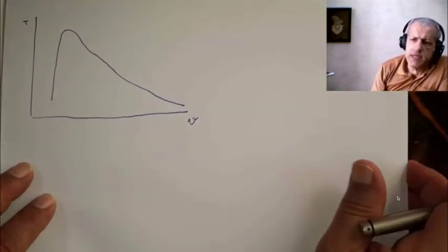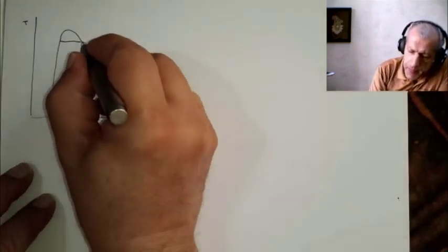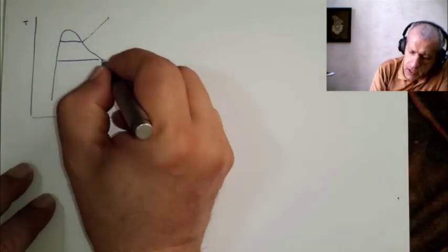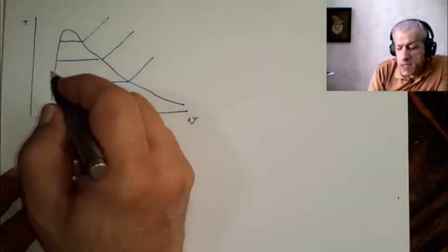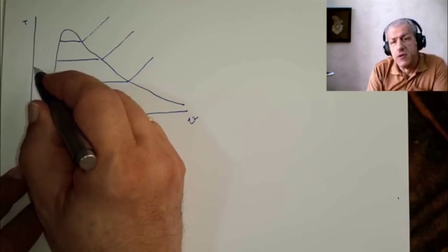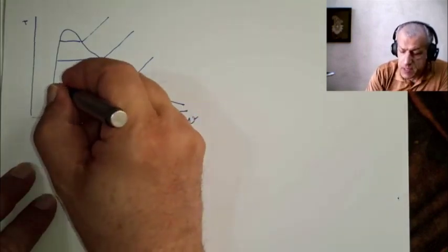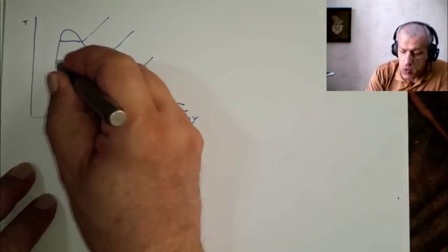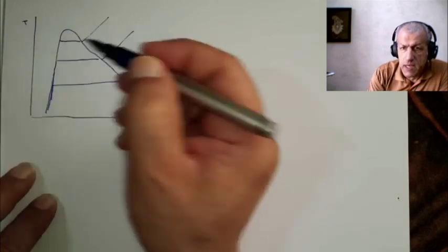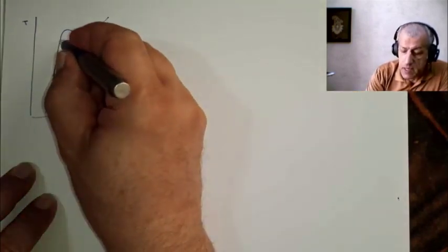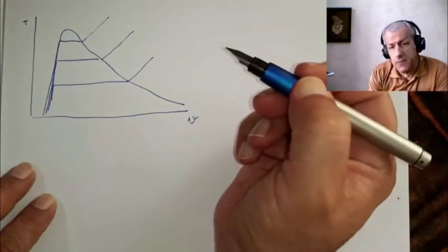So what we do is to draw a diagram just like before of the saturation line. And the point is this, that on the saturation line, of course, the constant pressure lines look like this, but in the compressed liquid area, the constant pressure lines are extremely close to the saturation line. I mean, even what I'm drawing here is an exaggeration of the distance. The distance is even closer.